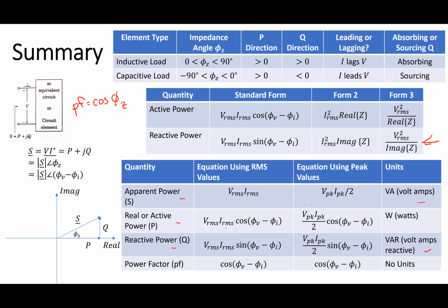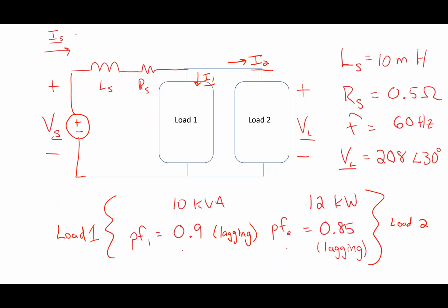Okay, now this is a pretty classic sort of problem. I'm saying a load is 10 kVA and all this sort of different stuff. When I deal with loads in general, this is what a utility would assume for a bank of houses. If I had 5 houses connected to a transformer, and we'll talk about transformers later, I'll say that they have a certain amount of kW at a certain power factor. That's the peak condition, and the utility is most concerned with the peak condition: what's the highest power you're ever going to draw?